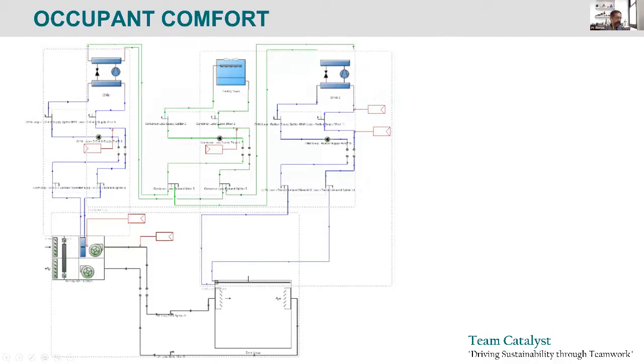The chilled ceiling or the radiant panel may need chilled water at a much higher temperature, 13, 14, 15, whatever your design condition is, and quite a small delta T, probably 3 degrees or 4 degrees delta T. So if you put in water at 13 degrees, then you may take out water at 17 degrees centigrade, okay? And what that does is, of course, it makes this chiller very efficient, looks very efficient, right? Uses very little energy. But be careful that you select the right kind of chiller. Not all chillers can provide such high temperature water. They may fail on high head, as it's called. Some of the modern chillers will do that.